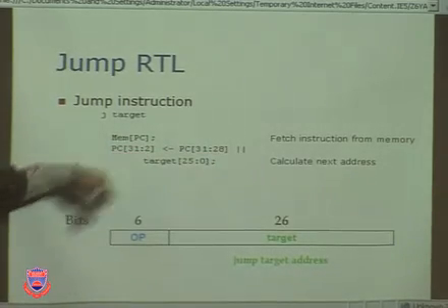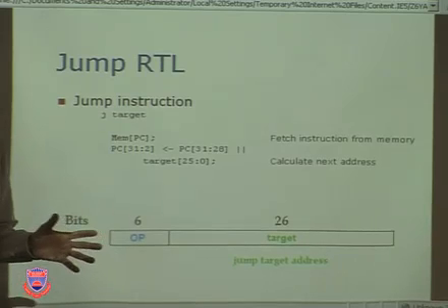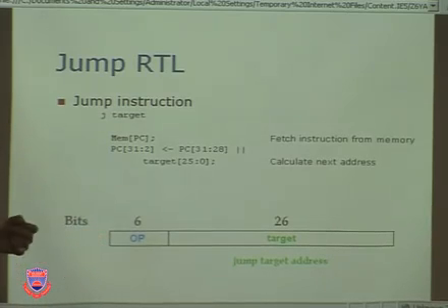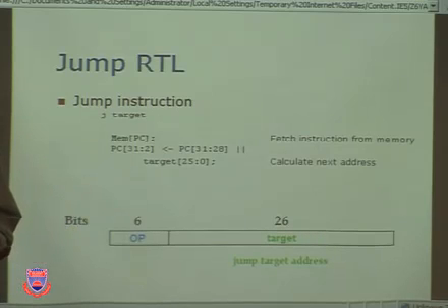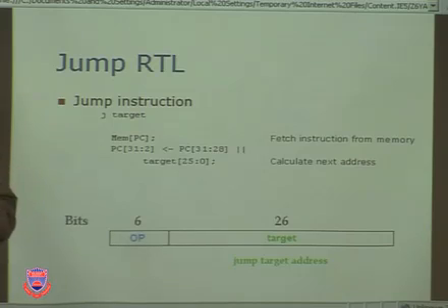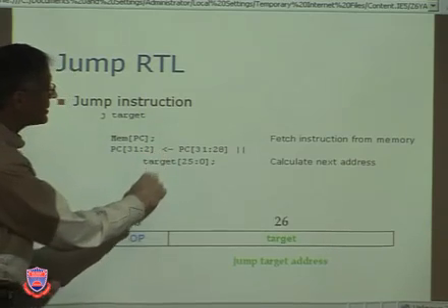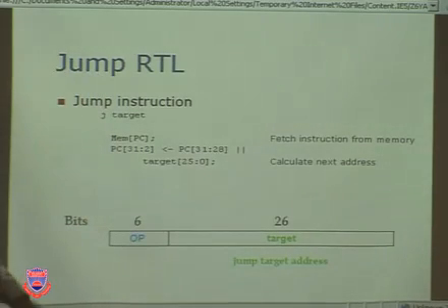And you notice that's only 30 bits, and you say, wait a minute, what about 32? And if you weren't here last time, you missed a very important point. We said the last 2 bits in addressing are always 00, because addresses of instructions, not data, but instructions, always begin on an even word boundary. So therefore, there's no need to have 2 more bits here which are 0, and 2 more bits here which are 0. We'll cut them down, and that'll enable us to save hardware and make the registers smaller and make the hardware faster. So here we go.